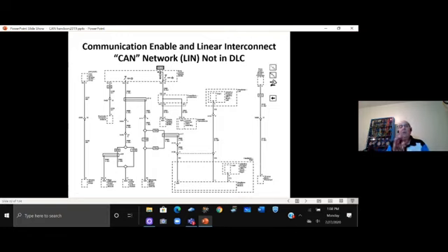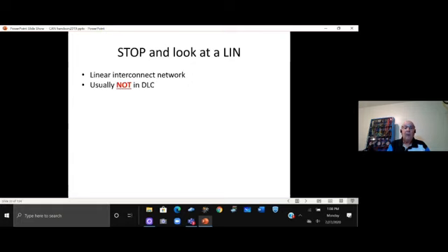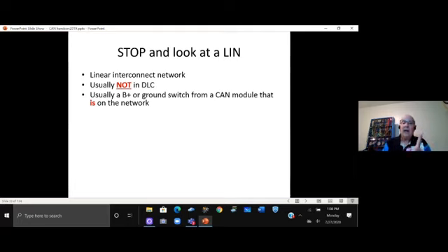Now, if I've confused you, good. No, just kidding. If I've confused you, I'm sorry about that. But LIN is not terribly complicated. The main thing to remember is when you're talking about LIN, it's an item which is usually not in the DLC. So you can't look at the DLC and say, oh, there's the LIN. No, it's not there. Usually there's a B+ or ground switch from a CAN module that is made red on purpose. So it's in the network and it supplies power to the module or whatever, okay?